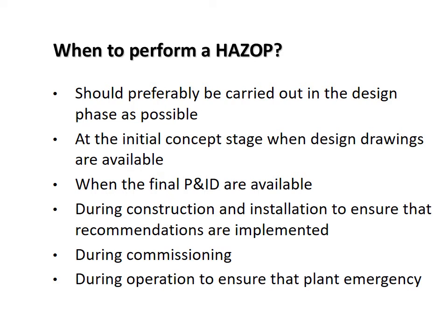Now, when is HAZOP required to be performed? It should preferably be carried out in the design phase as early as possible, at the initial concept stage, when the design drawings are available, when the final P&ID are available, during construction and installation to ensure that recommendations are implemented, during commissioning, and during operation to ensure that plant emergency procedures are in place.